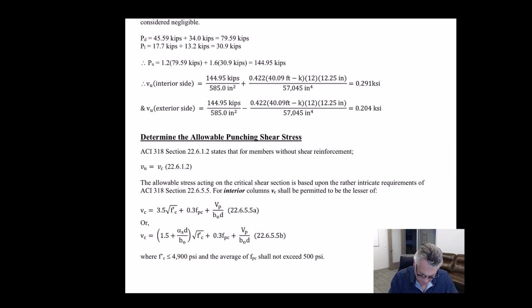Now, just like we did before, we're going to ignore these because we don't feel confident enough that we know exactly, right at the edge of the critical shear plane, what that vertical component of all of our pre-stressing is. It's kind of a scary thing to include to help yourself when you don't know it that well. So I think PT data, I think all software, just ignores that part of it.